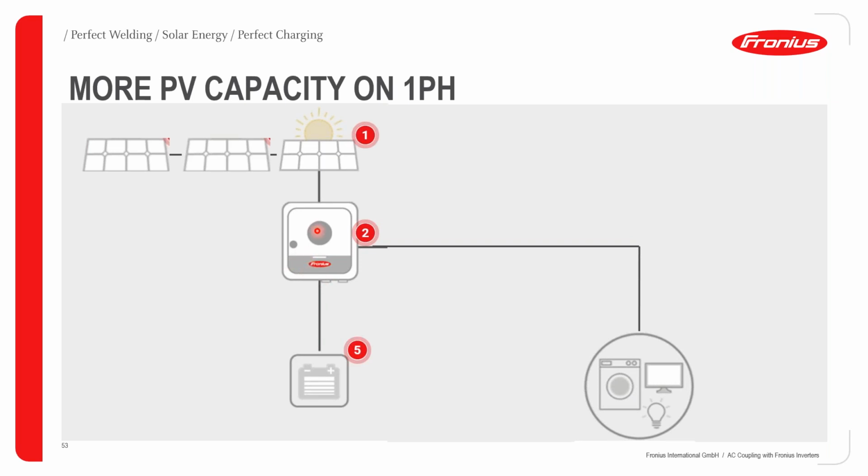So mind you, with the DC battery inverter, this of course increases the inverter capacity, because the inverter capacity basically takes note of the capacity of all the inverters in the system. So if you have a DC or battery inverter in the system, it of course has an accumulative effect on the capacity. Why I'm saying this is because for some countries or regions, we have restrictions for single phase systems. We have countries that actually have a power capacity cap of 10 kilowatts, for example.